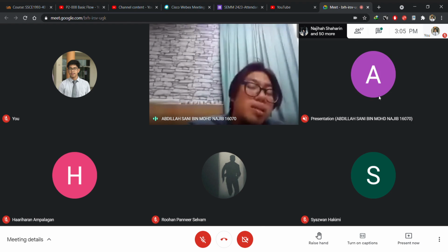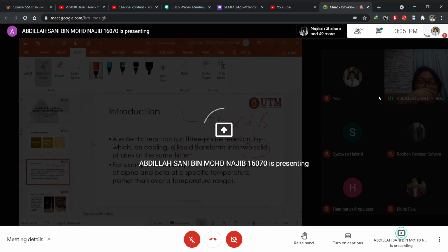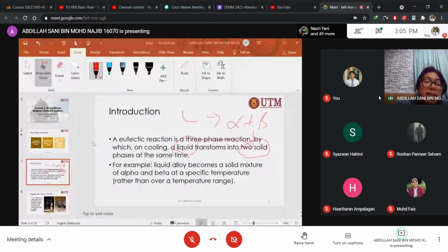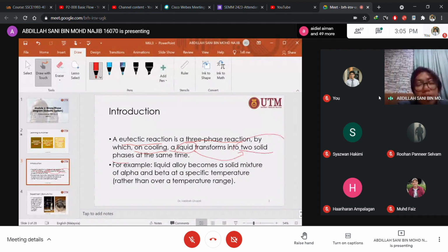Okay. Sorry. Thank you. So okay, we go line by line again. What we were defining was that a eutectic reaction is a three-phase reaction, which means it involves three phases. During the cooling, a liquid transforms into two solid phases, not one but two solid phases.